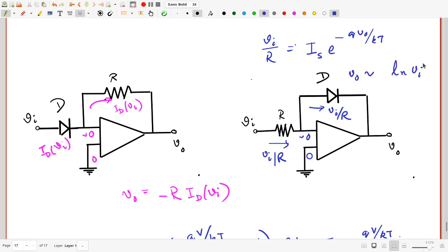But basically what you have is these two circuits: this one produces the exponential function and this produces the log. But now that you have a way of producing the log, you have a way of adding and subtracting, you have a way of multiplying by factors, and you also have an exponential. You should realize you can do raising a voltage to a power, multiplying voltages together, dividing one voltage by another. All these can be achieved by combining these circuits with the adder, subtractor, multiplier, and so on.